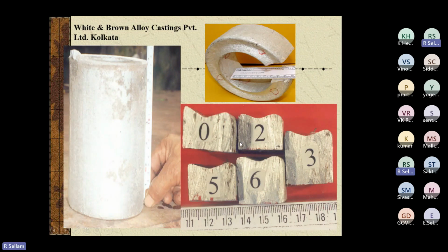This is the outer side, because during casting, the outer side gets detached from the mold wall, so the heat transfer rate is less at the outer side compared to the inner side. The inner side sticks due to internal shrinkage, then it gets adhered to the internal core side.